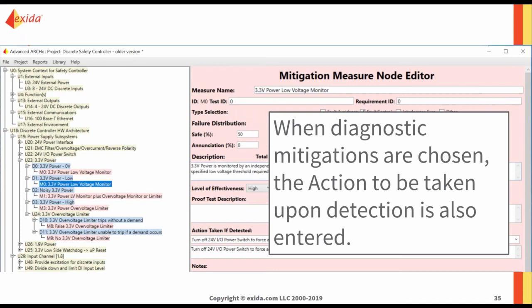We went to run the final test. We simulated a failure and the current froze, the output froze, for example, and did not go to 3.6 milliamps. Disaster. The whole project is basically shipwrecked.